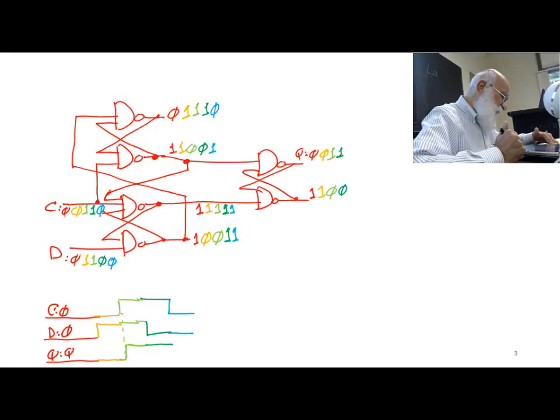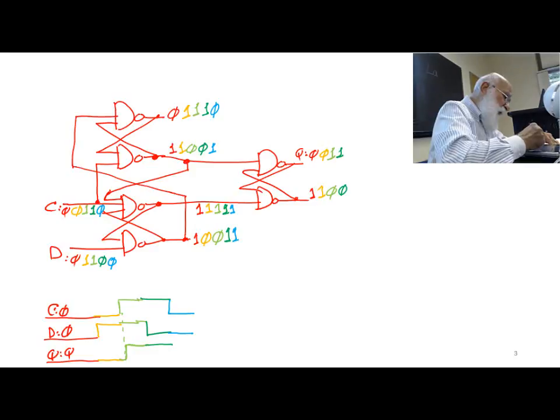All right, so what do I have here? I have 1, 1 on the inputs of the cross-coupled NAND structure of the output, and let's analyze the top gate. There is a 1 there, and then there is a 0, which is the lower gate, and therefore the output remains 1.